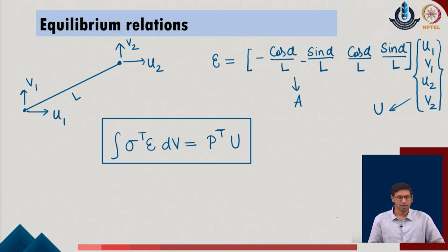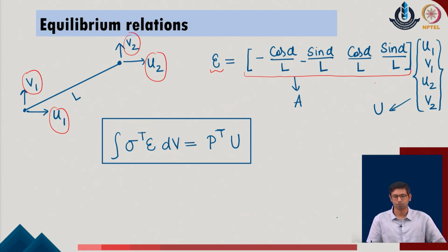Now, moving forward, we have the general expressions which we can define. We have said that epsilon, which is identified as the strain in the given system, can now be represented in terms of the general local and global displacement vectors of the given system. So, we identify the global displacement values of the system which have been located over here, and then we consider the transformation of the linear relationship with respect to the general angle alpha which the member makes with the horizontal axis x of the global direction.